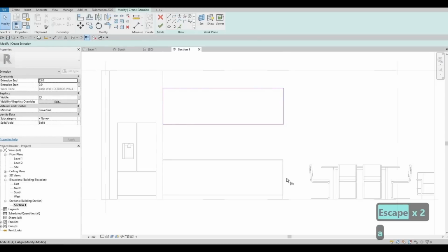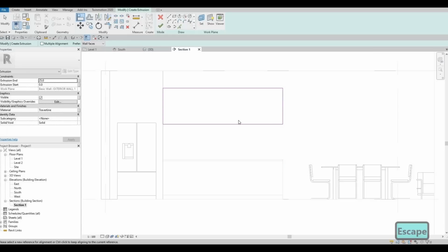We're gonna use AL, which is align, to align it all the way to the bottom so that everything will be uniform. And then here we're going to extrude it from the wall around 500. We can also do that around 450 probably. So let's do 450 first.